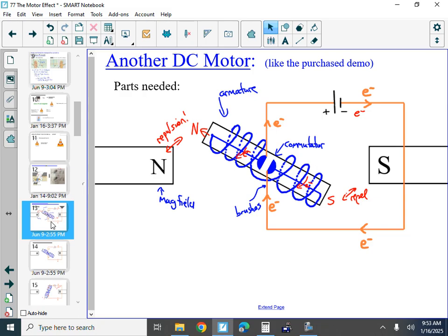Another type of motor that I have, so I have a model of it here. A coil of wire like this, and then the connectors, the ends of the wires are there. If you picture this setup right now, it's easier to think of the coiled conductor's magnetic force or magnetic direction. So we've got electrons flowing out of the battery here, electrons coming in, electrons going through this wire, and now it's up and behind and down in front. So curl the fingers of your left hand with your fingers down in front, closest to you, and your thumb automatically aligns to be towards the left. So this is producing a north.